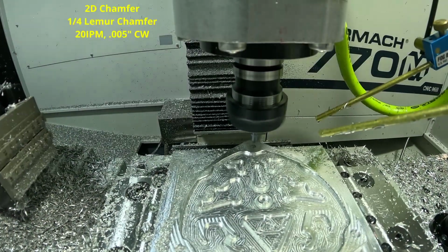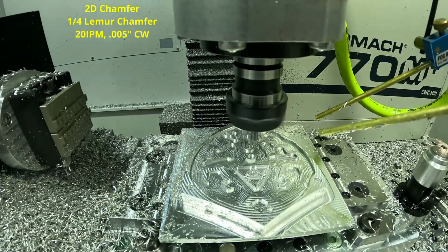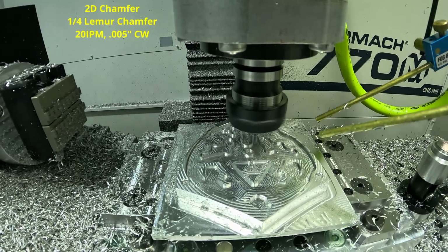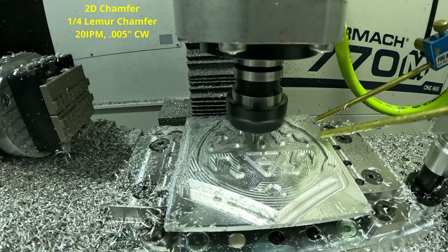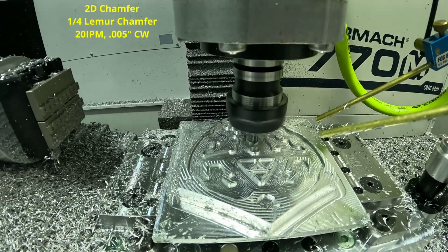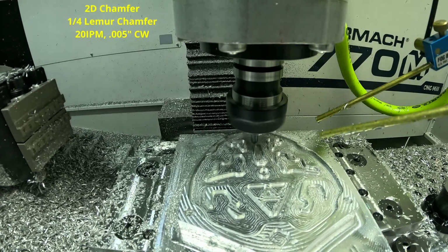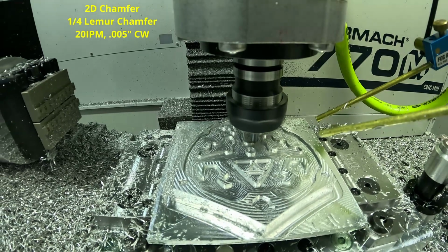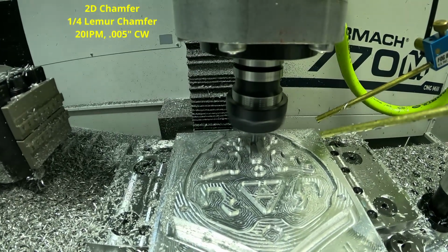So here's that chamfering toolpath. It's the same tool, 20 inches per minute. We're just going 5 thousandths for a chamfer width, so we can just kiss those 30 thousandths walls and remove any sharp edges. Again, in my experience, after I poured the epoxy, it usually doesn't go 100% flush with the surface, so you can sort of fill the tops of those walls. So I just wanted to make sure that there are no burrs.